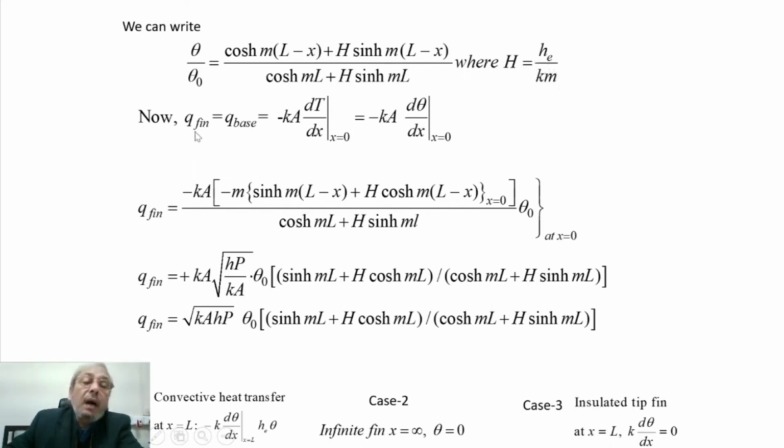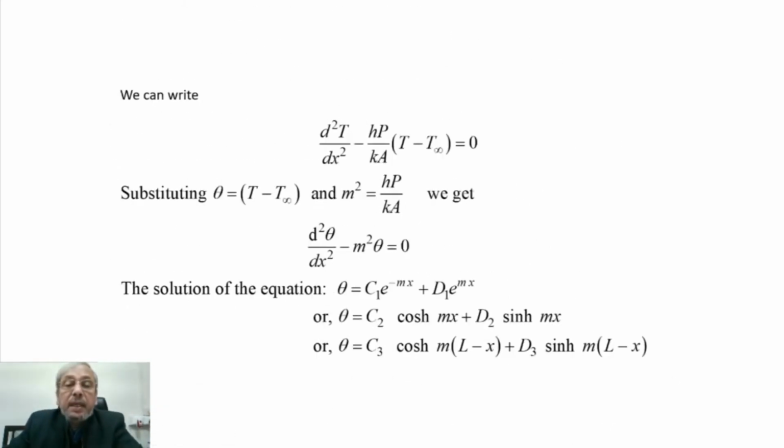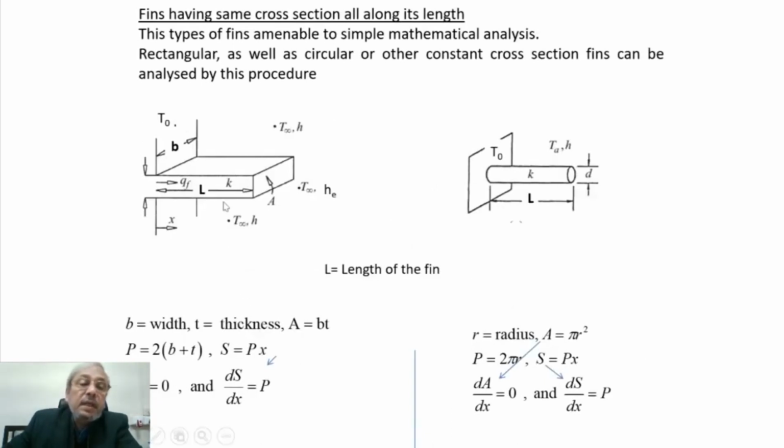Now the heat transfer through the fin is basically, the fin is cooling. So the mechanism I can once again highlight: the surface will be cooled by the local fluid, the local ambience, and that will promote heat transfer and bring down the temperature, and from the base energy will flow through the fin.